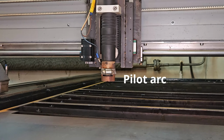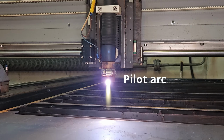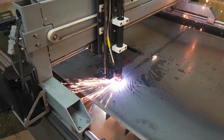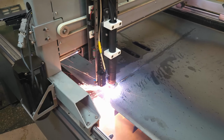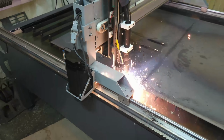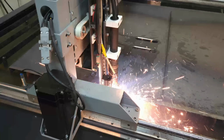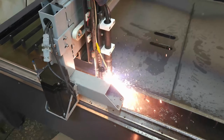First of all, we have arc current. This setting primarily defines if you will pierce the material at all. Let's start with what exactly an arc current is. A plasma arc is basically a superheated ionized gas, usually compressed air, reaching extreme temperatures. From the electric side, it has a voltage and current. Voltage depends on the length of the arc, and current is the parameter we set. The higher the current, the more powerful our arc is.